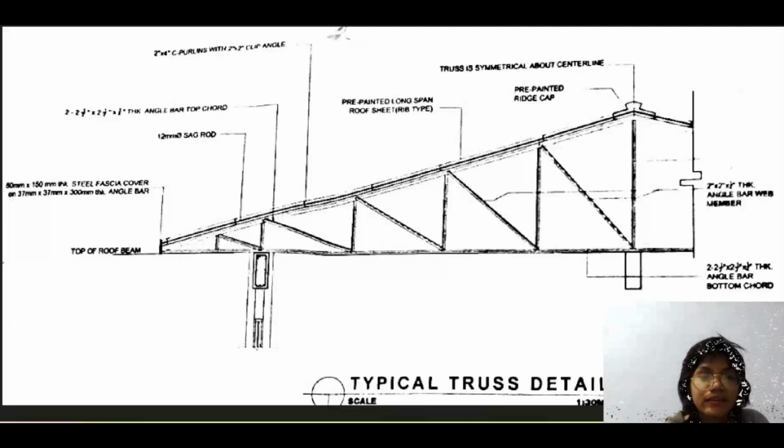consists the top chord. The top chord is used to create the upper perimeter of the structure or the roof. The top chord is configured to resist live loads such as those applied during construction, as well as wind loads, snow loads, and others. So, the sag bar or sag rod is provided in purlins to support the section in bending about the minor axis. They provide the lateral support to purlin to prevent sag in the direction parallel to the sloping roof due to vertically applied loads and reduce their tendency to bend laterally and twist.